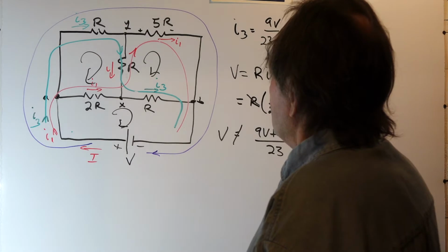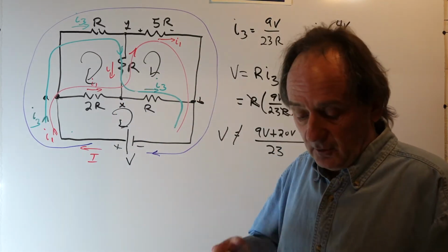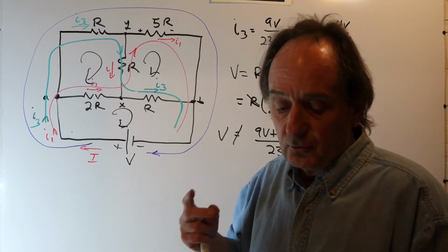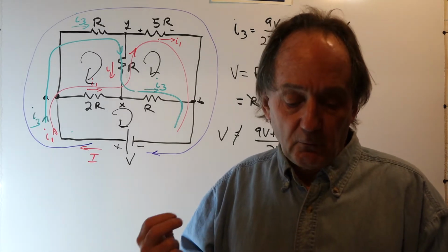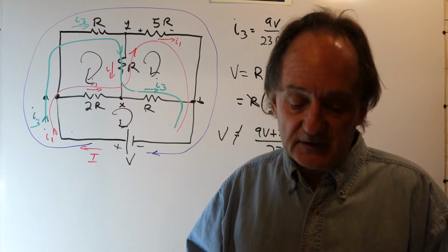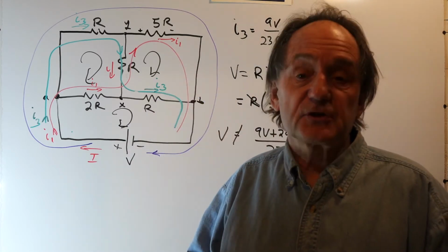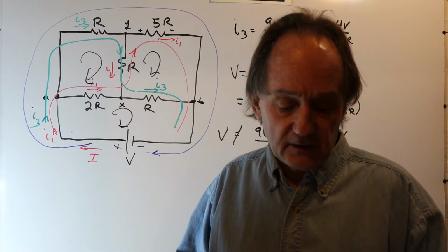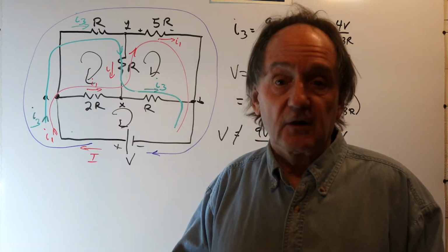Now, in the 2R case, they were indeed symmetrical, and it led to a consistent solution. But the two loop currents, you'll find a solution when the currents are indeed symmetric, but will fail otherwise. If there is no symmetry, the solution will fail, as it did in this case when a 5R resistor was introduced, which destroyed the symmetry. Without further checking, one might come to the erroneous conclusion that the current symmetry still exists, where clearly it doesn't.